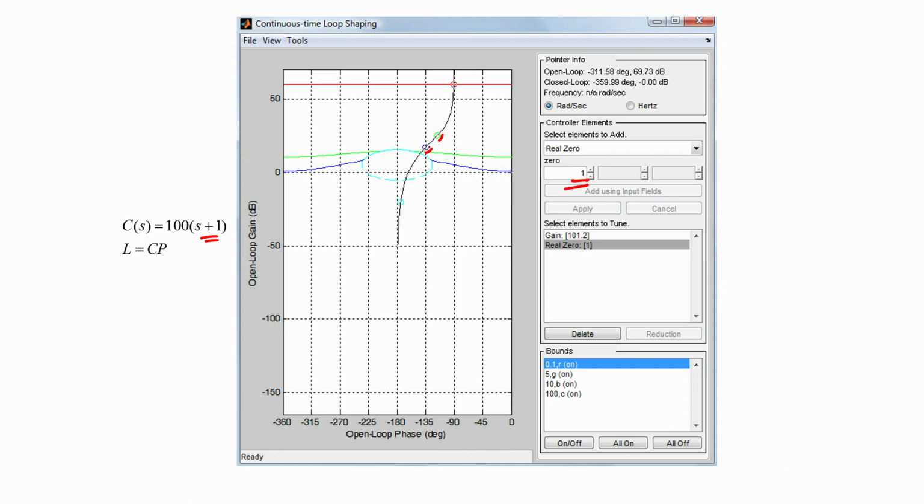The only concern now is with stability, because the loop still passes through the forbidden circle, which indicates that our transmission function will assume a magnitude that is greater than 3 dB, and hence our closed loop system will have a much smaller phase margin than what we had initially planned for. To address this issue, we try to move the Nichols plot further to the right, which essentially means that we have to add a phase lead.